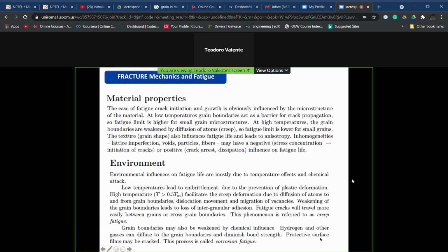In some cases, as we have seen in terms of general mechanical behavior and crack propagation inside, for example, ceramic materials, they could also have some positive effect if they contribute to stopping the crack propagation or to inserting inside the material some energy dissipation mechanism. So microstructure is very important. Being fixed the chemical composition of the material itself, the fatigue life can be sensibly affected by this feature.